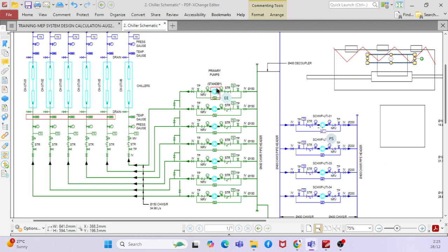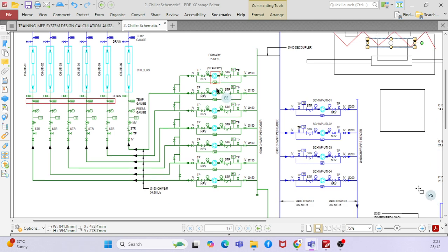See, what will happen, this particular pump will normally be a variable pump because it's a building side pump, right? So the building side pump will be variable. Why is it variable? You have an AHU consisting of a PICV. The PICV will vary the flow rate based on the required demand, right? So when that varies, the flow rate will adjust. Typically, the worst case as per the building load is 50 liters per second, but due to the different orientation and applications, AHUs and FCUs can go low speed, medium speed, or high speed.